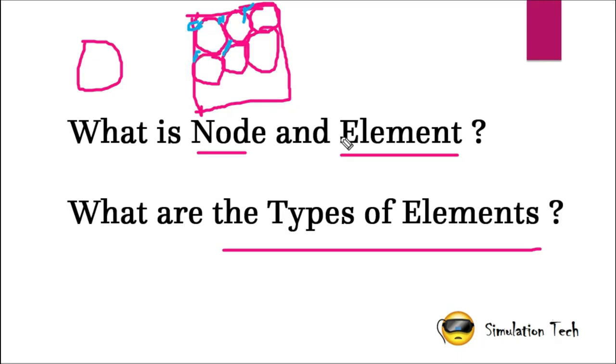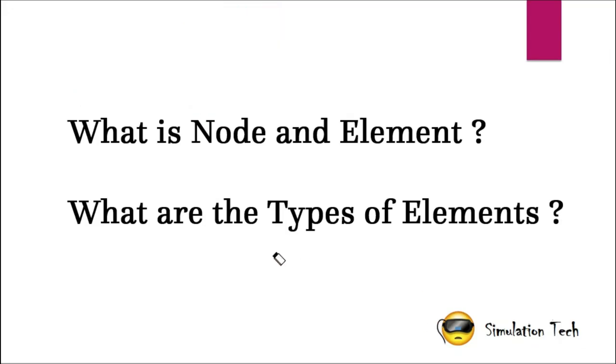So you get a larger number of errors over here. Already we have so many errors in discretization. If you use a circle as a discretized element, it is not suitable to capture all the areas, spaces or volumes in our model. So we don't use all shapes to discretize a model into elements. We have a certain set of rules that we have to follow. That is the main rule in FEA, right? So let's see what different types of elements are available in FEA. Let's get into the next slide.